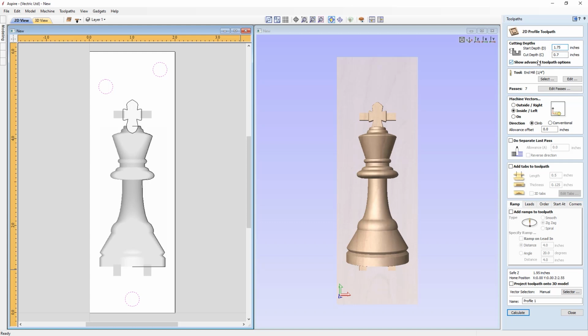Now also, it's important to remember that your material block will not be on your machine at this time, so we can safely avoid this distance without any problems at all. The rest of this is all going to stay exactly the same. We're going to use that 1/4 inch end mill. We're going to cut inside that line, and we're just going to go ahead and call this dowel holes. And then we need to make sure that we don't forget that this should be in spoil board, and that will remind us to do that.